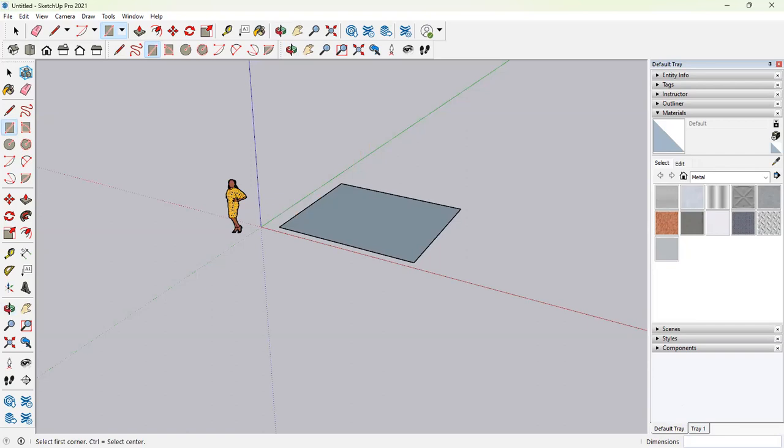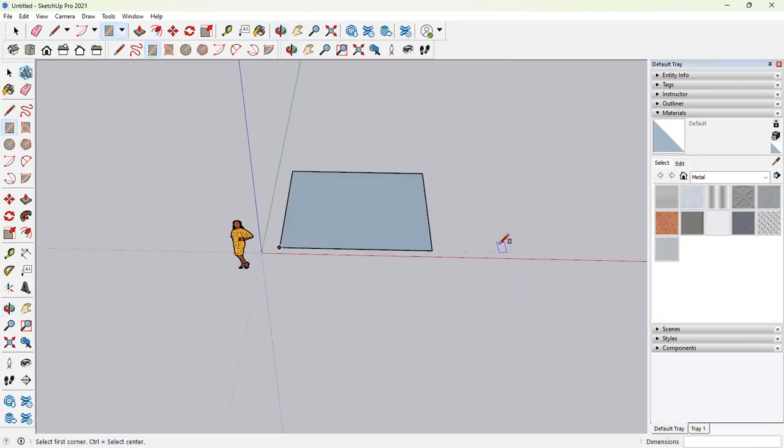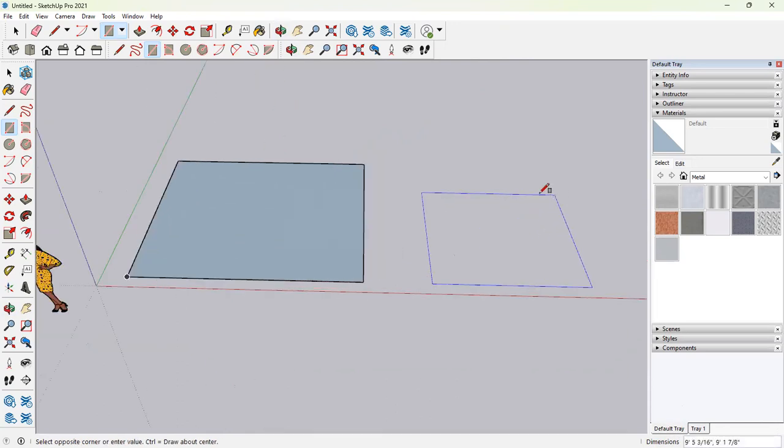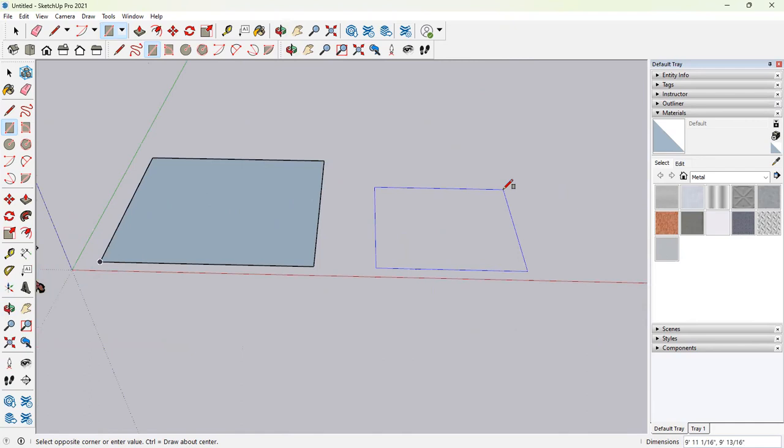Now, if you see on your right-hand corner, there is dimensions. So here is where you enter your dimensions. You don't need to enter it physically. You have to just enter into the command, activate your command tool and type. So let's say for a line, if you want to draw a 2 meter line, that's 2000 mm, you'll start, I'll snap it with the arrow key to the red axis and I'll type in 2000 mm and hit enter. So it will draw you a 2000 mm line.